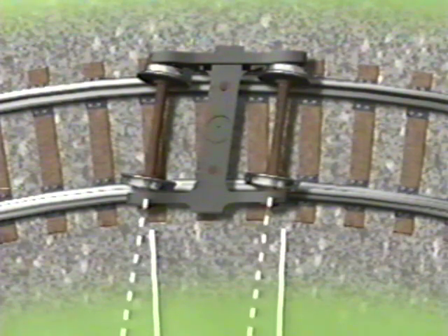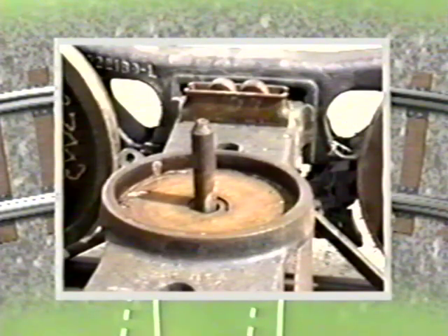The scenario first showed the wheel set developing a large angle of attack. There are several factors that can cause this problem. First, the truck may not turn properly in the curve and warp, causing both wheel sets to develop large angles of attack. Earlier, we said that excessive turning resistance can come from high center bowl friction, tight side bearings, or interference from fasteners.